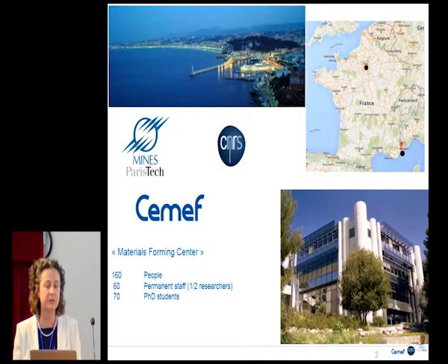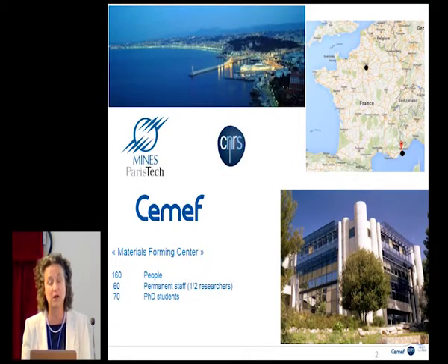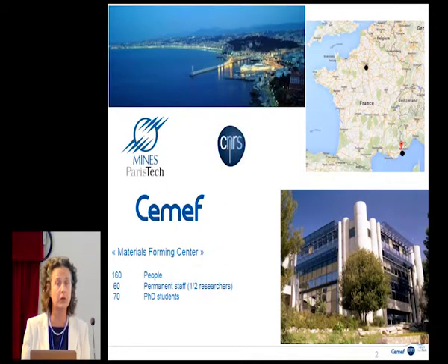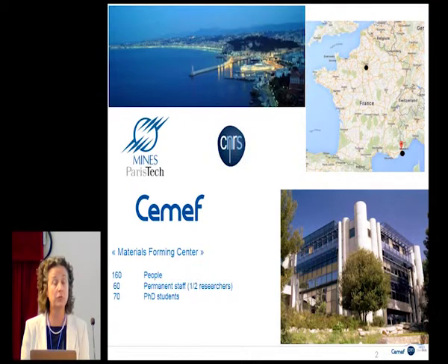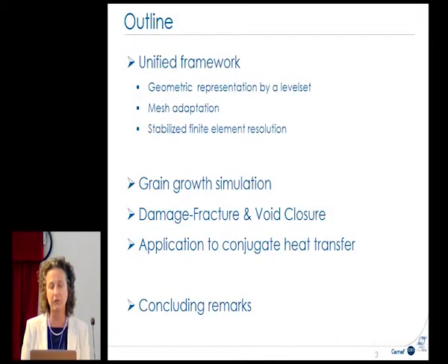This grain distribution is very heterogeneous depending on the process, and this is a very large difficulty for the final part. But we also sometimes have the evolution of voids, and this evolution of voids could also lead to some damage, and it is also very important to be able to predict this. And of course, the macroscale is all the process around heat treatment, including heating, but also quenching. And this is also very important to predict the final properties of our part.